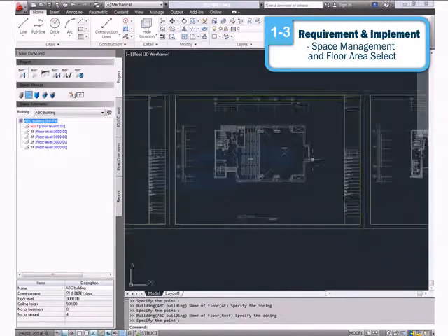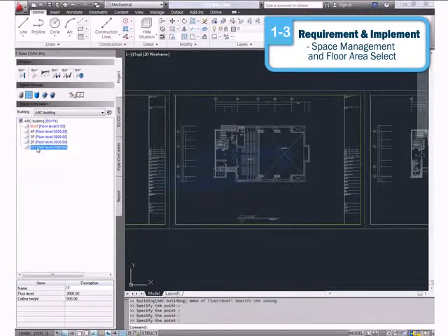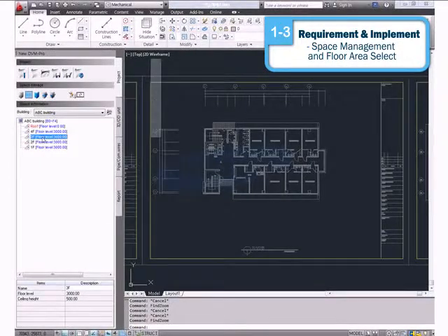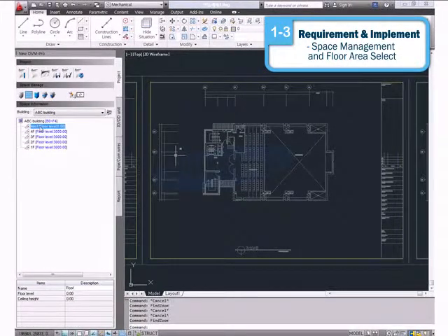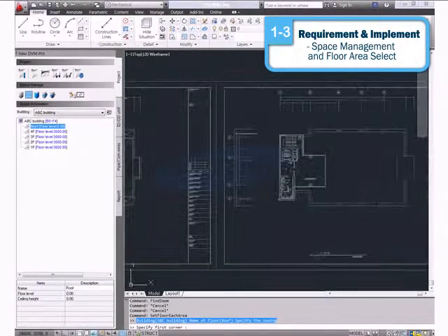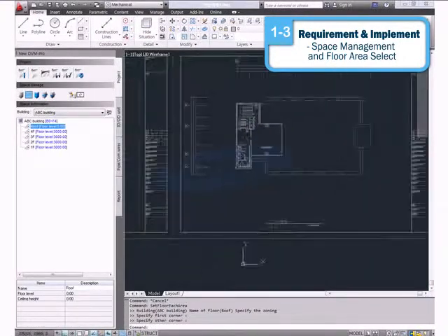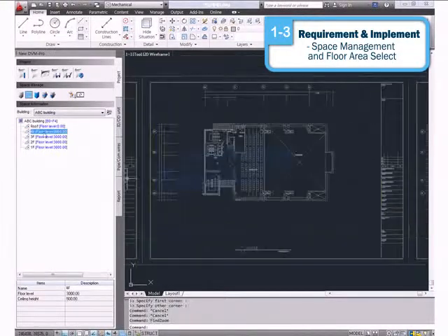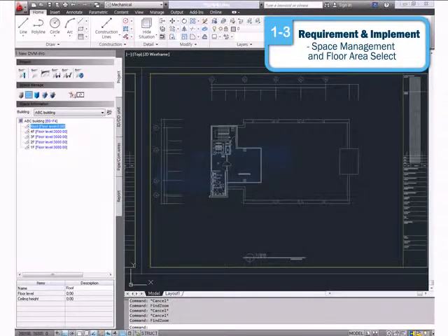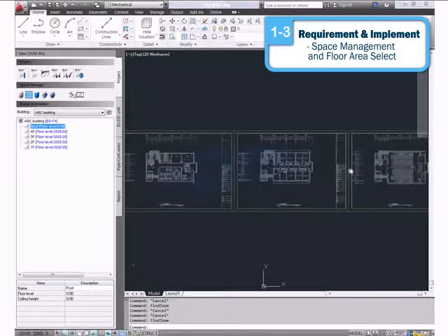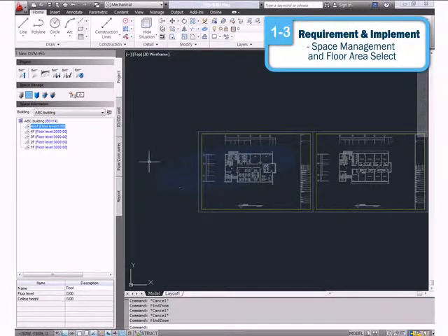Let us use the second floor area selection method for the roof, which is called floor area individual selection. Click Roof from the space information list, and click fourth Specify the Zone each floor icon on the space management section. Click top left corner of the floor plan for the roof, followed by clicking the bottom right corner to set the floor area selection. When you click icons on the DVM Pro, pay close attention to the commands that appear on the AutoCAD command display before using them.